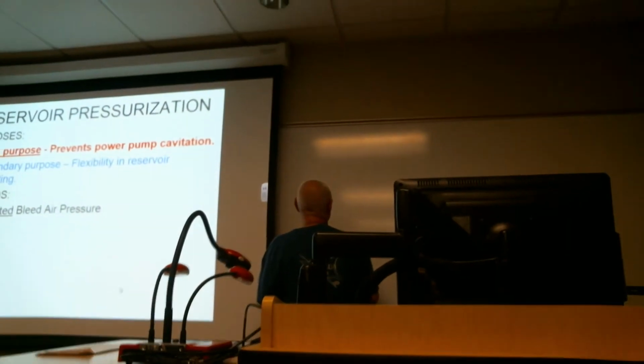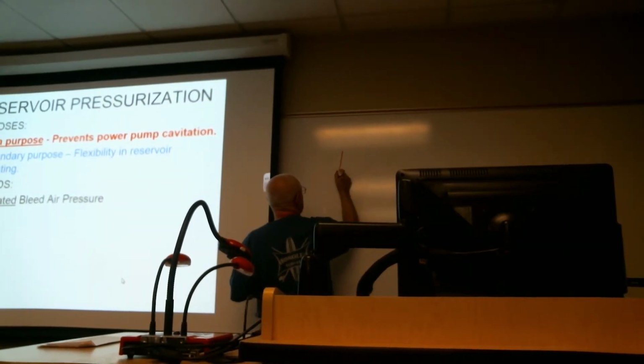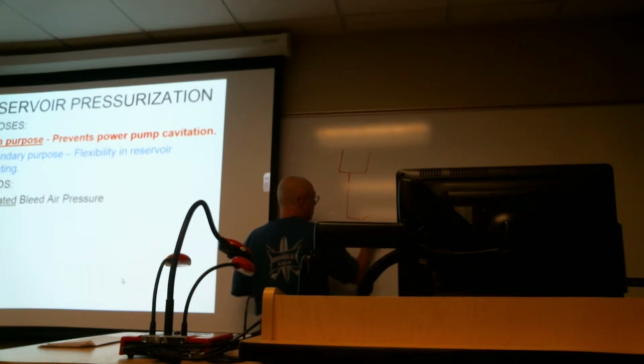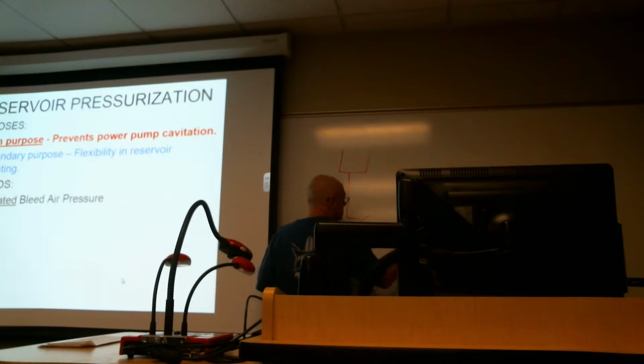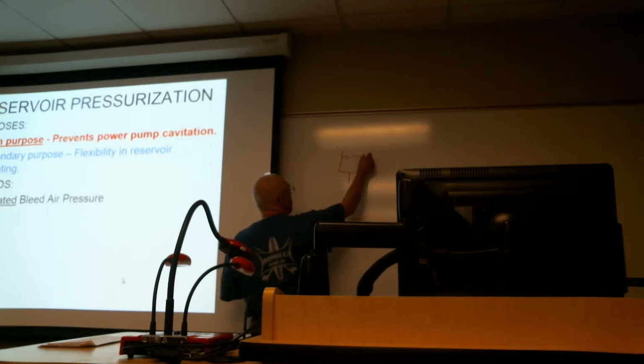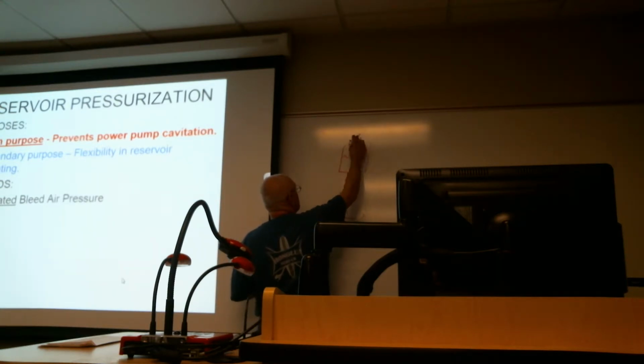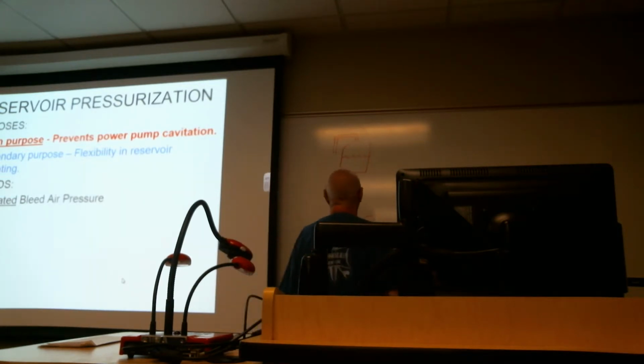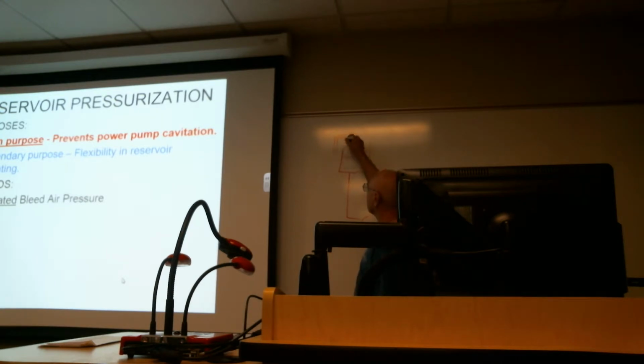When you've got a simplified hydraulic circuit that kind of looks like this, you've got a reservoir, here's the pump, and it goes downstream to a pressure regulator, and then ultimately goes to components. The reservoir itself is usually a vented reservoir. We've got maybe a vent opening with a tube coming down the side of it. And the idea is you've got atmospheric air pressure that's able to push directly on top of the fluid.